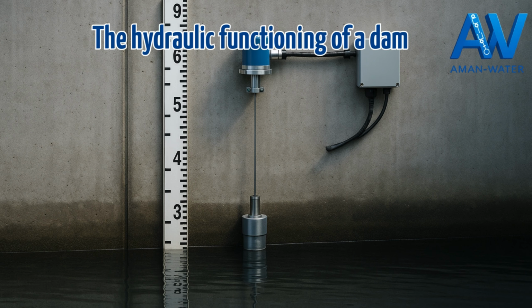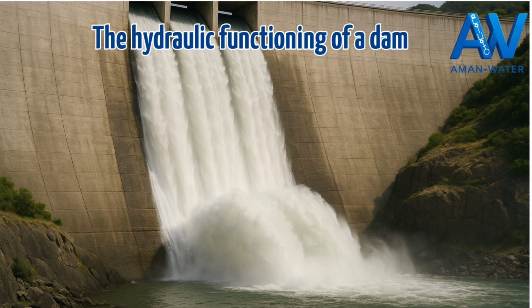Hydraulic functioning is not limited to retaining water. The level must also be managed. The reservoir is not always full. Depending on the seasons, rainfall, snowmelt, or downstream uses, the level varies. Engineers always keep a margin to anticipate floods. With gates, intakes, and the spillway, they can adjust the flow and maintain precise control to avoid overload.